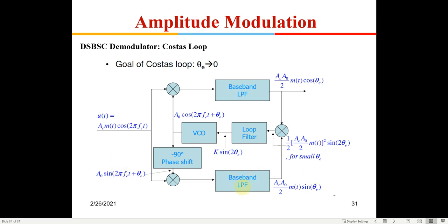So cos A into sin B you are doing, right? Then again you pass it through a band pass filter. So again cos A into sin B, right? That is sin A minus B. And then you are passing it through a low pass filter, so that the 2 FC components will get eliminated there, and you will only have the difference of these two signals, that is the theta component coming here, that is sin theta.